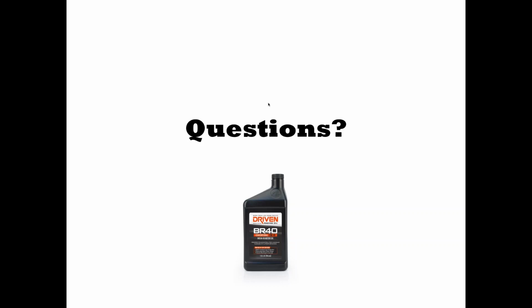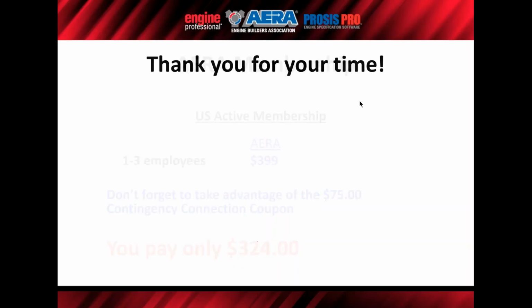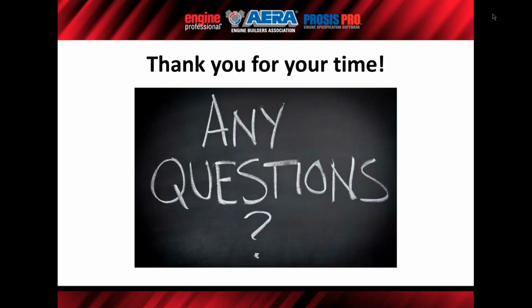Well, thanks for the question, Doug. And really, you're kind of hitting on all of them. And it is the package. That's the key thing to keep in mind, that when you go to tighter bearing clearances, you need to go to lower viscosity oil. And that by itself tends to bring down oil pressure. You've got to remember that oil pressure in the end is just a result of oil flow. It's resistance to flow in the engine that reads on the gauge. So you can have flow through the engine with very low pressure.